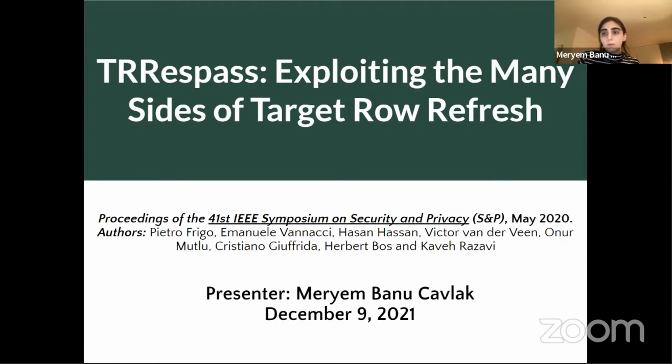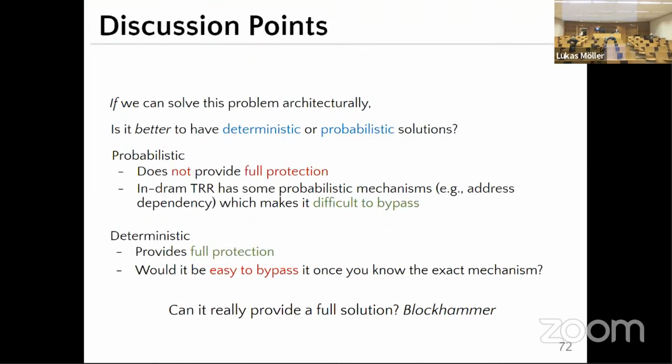Given a probabilistic approach, if we can just correct the small number of bit flips that we still have with something like ECC, then we're basically in the clear, right? Since the problem with ECC is that it might not be able to catch all of the bit flips, if we can just limit the number of bit flips sufficiently or have them be so unlikely that it's basically guaranteed that we can catch them.